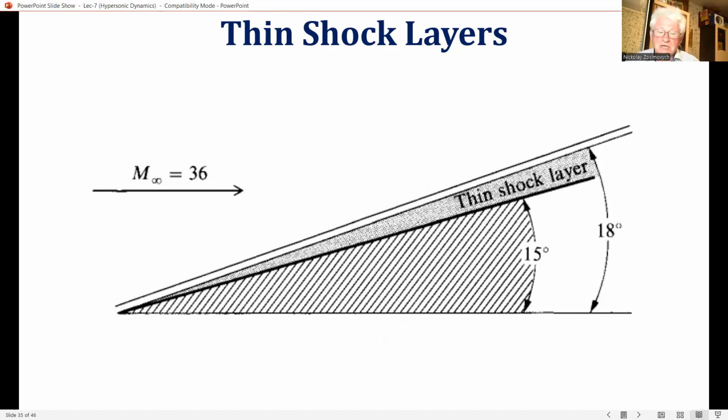Maslen's method is chosen here because of its simplicity and because of its frequent application, even today, for the approximate analysis of hypersonic inviscid shock layers. Moreover, Maslen's method gives results for the flow field over blunt as well as slender bodies, and therefore it makes a nice intellectual as well as chronological bridge between the recently discussed classical material and the more modern computationally based blunt body solutions.